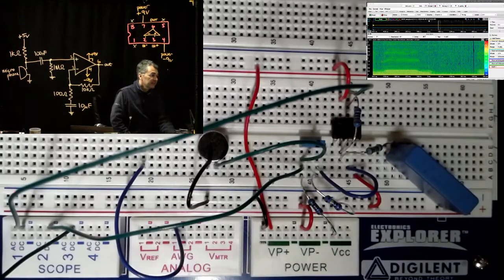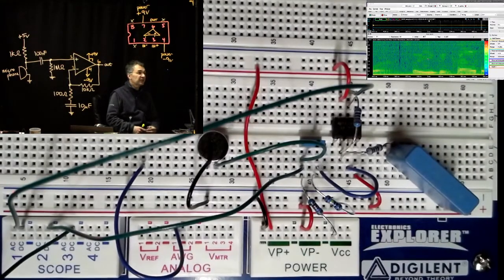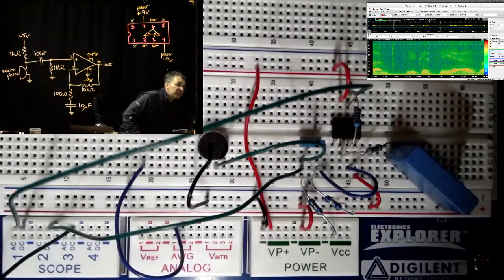And then in each time bin, on the vertical axis you have frequency, going from 0 up to 4 kilohertz in this case, which is exactly the range you want to look at for identifying human speech. And then there's a color map, so the magnitude of the amplitude within that frequency and time bin is shown in color. So you can see things light up. As I'm talking, you can see that the pattern changes depending on the pattern of